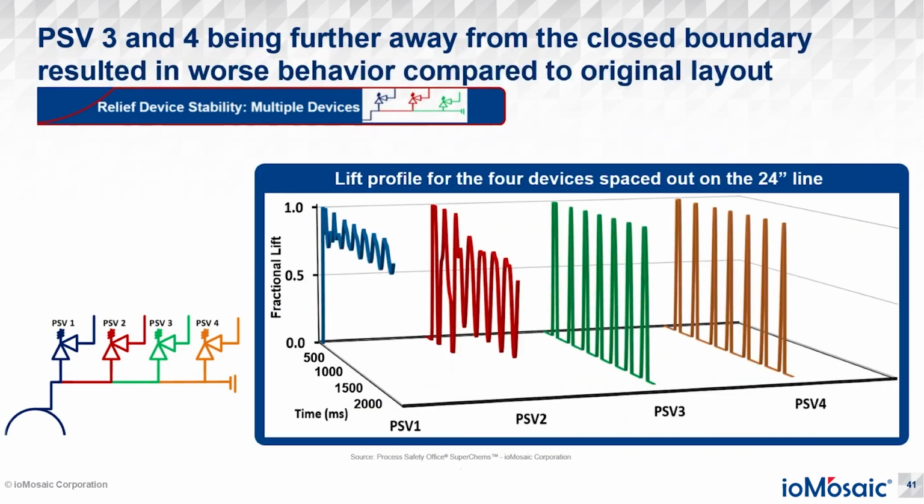So if I continue, with that new layout, again, we can see the blue valve, the low set pressure PSV1, pops open. We have that flutter. PSV2 chatters a little bit, gets a bit more flutter, almost like a magnitude, a bit more amplified flutter. PSV3, PSV4 unfortunately still chatters.